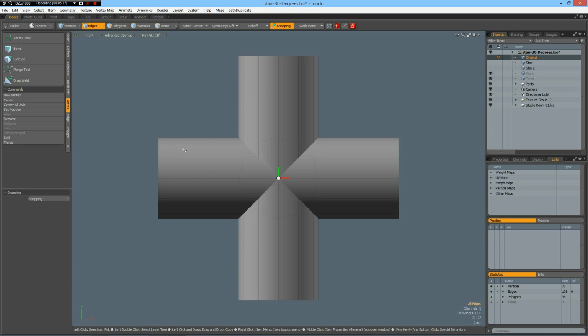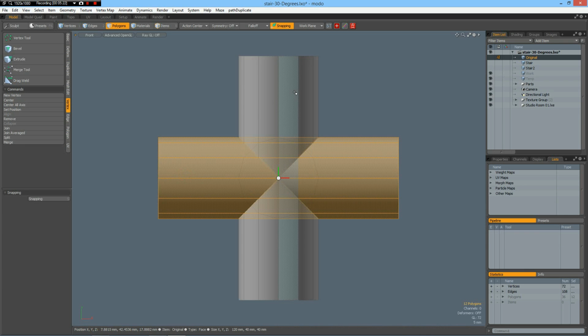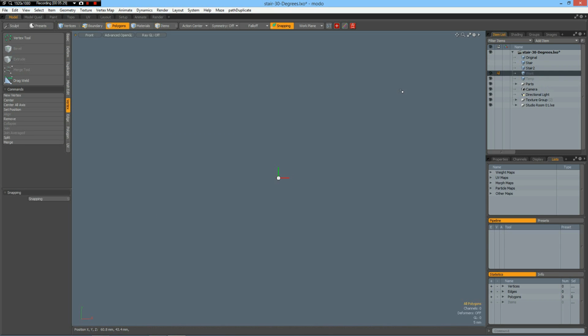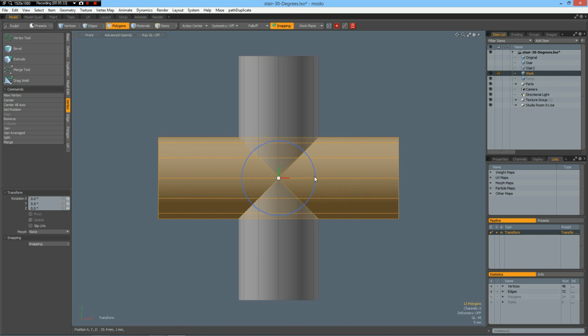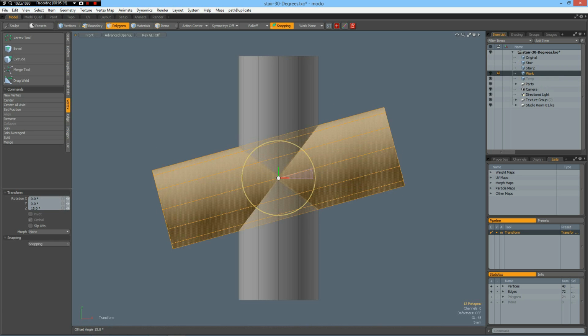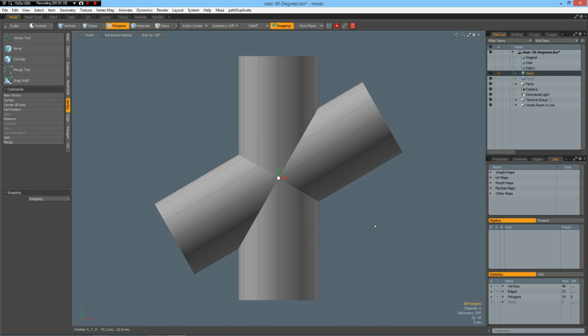Then I go and do the 30-degree T and 30-degree cross. So select these, Control copy, go to the work directory, Control V, and now I rotate this by 30 degrees. Then Shift C and make sure you have angle snap, which means snapping must be enabled, and you have an angle of 30 degrees.